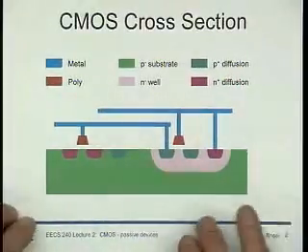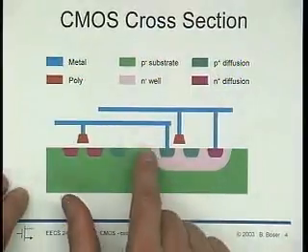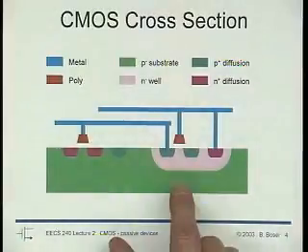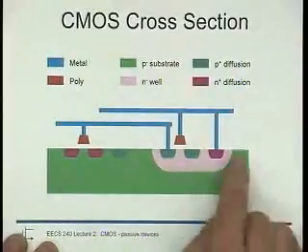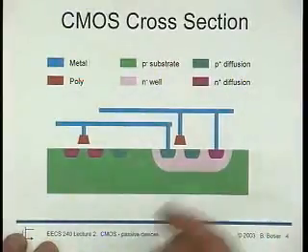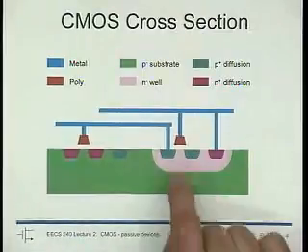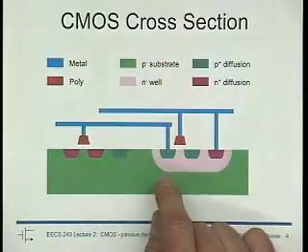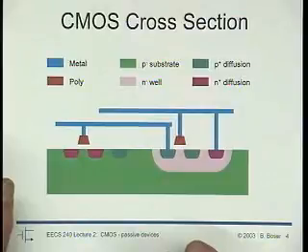So we can see this stuff from a cross-section right away. It's kind of trivial, right, obvious. So if we want to make a PMOS device, then we need an N-well that is somehow put into the substrate. There are lots of ways to do that, right? Again, for that you can take another course. And then we do the same thing. Now here it's even getting more interesting to look at the cross section, because if you remember 140 SPICE, right? How many terminals does a transistor have in SPICE?